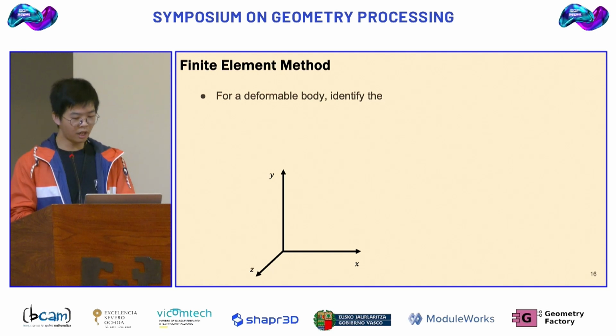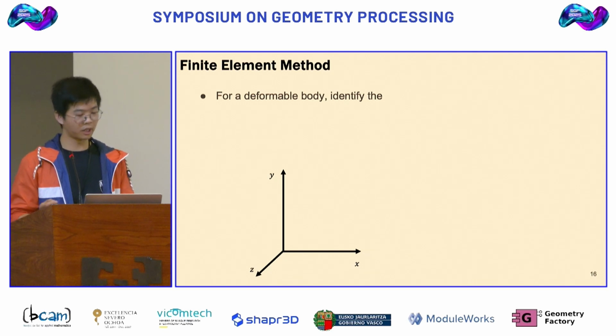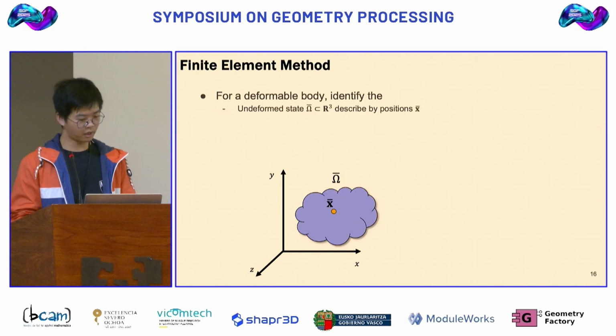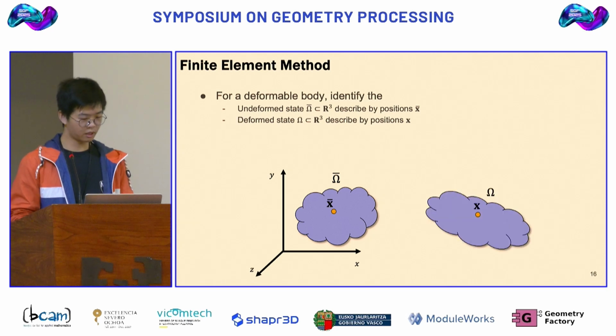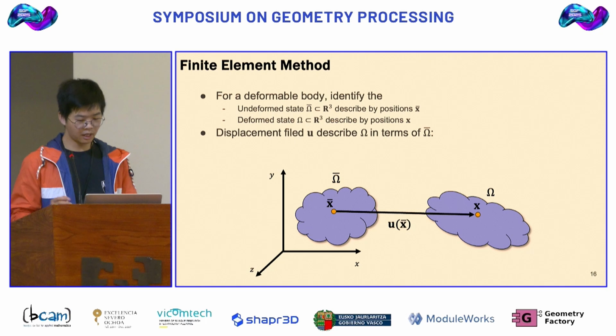And then for deformable solid medium, the finite element method is the usual way to simulate the deformation. And to do this, we start from undeformed states described by x bar, and its deformed states by x. And the displacement u describes how it deforms from undeformed to deformed states.